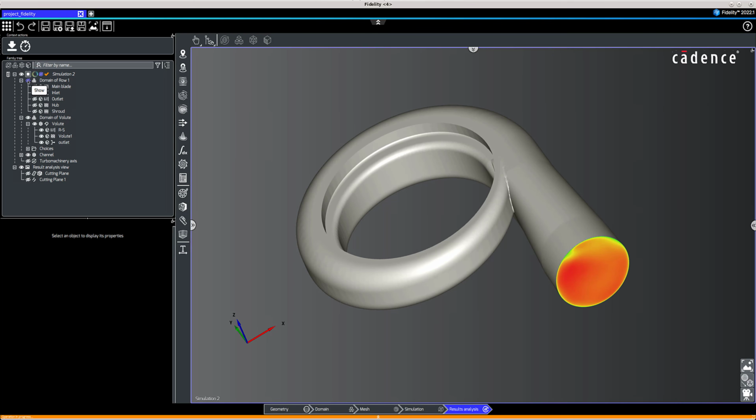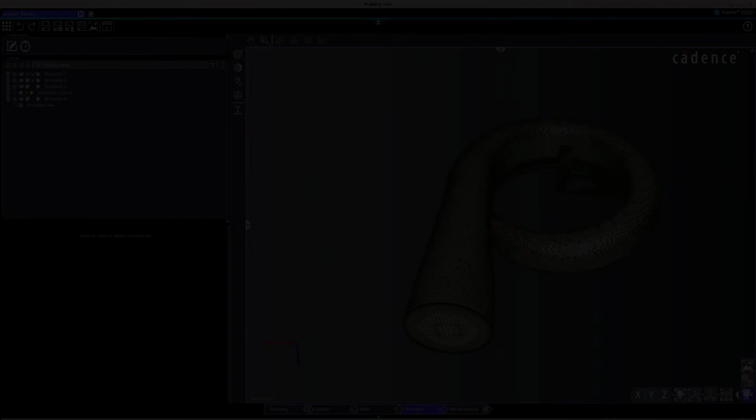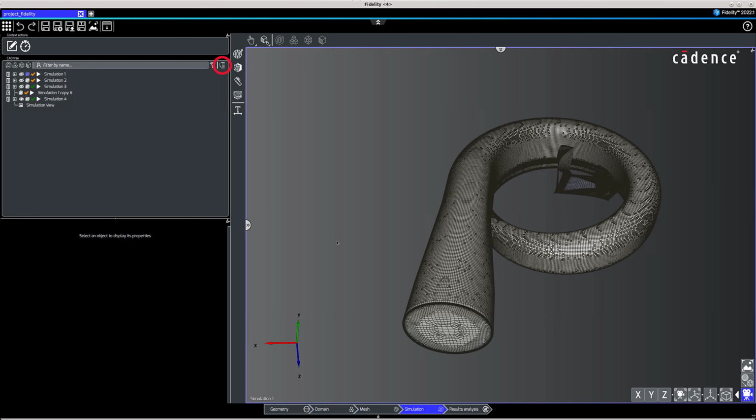And let's look at one final useful feature, which is a Locate Entity button beside the Tree Filters menu. It can be used to recursively locate the selected entities in the tree. First, make sure that the proper 3D selection mode is activated in the selection toolbar. For instance, if you would like to search for a boundary in the tree, activate the Boundary Graphical Selection mode.